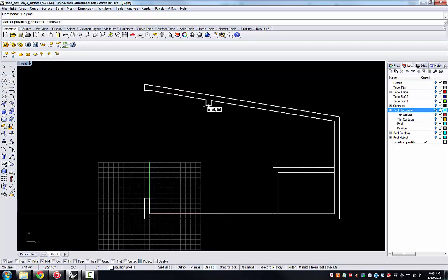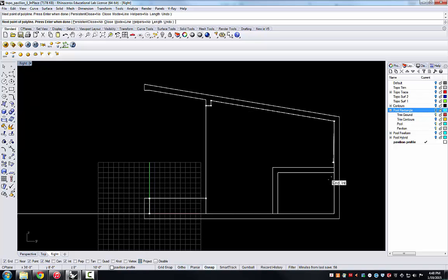To do so, I'll draw some reference geometry and profiles exactly as I did for the straight pavilion, creating a polyline end wall to cap this off. In fact, I'll create both polylines while I'm here, simply repeating the steps I used in the previous example, but doing it more quickly now.